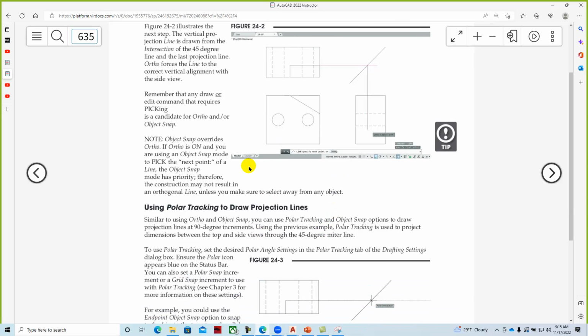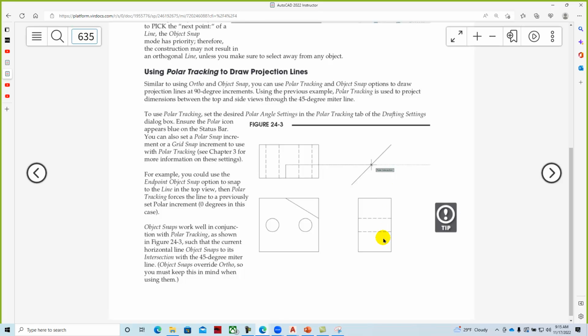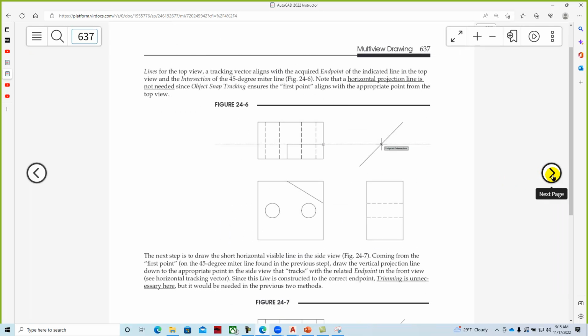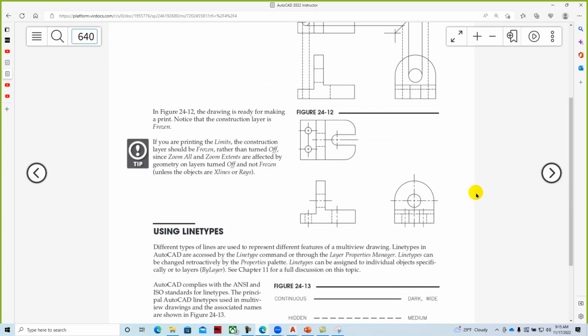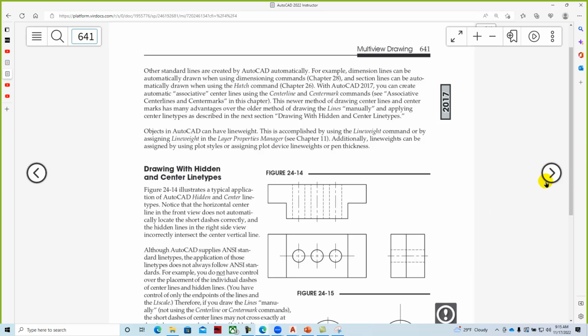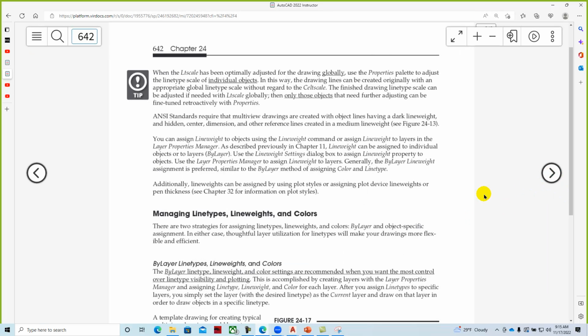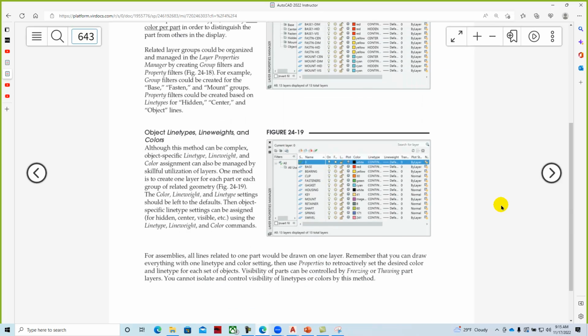And it's called orthographic drawing, and we can use these projection line techniques. These go back to when we used pencils, where you'd have the front view line up with the top view, and then the top view, if you were to bounce off a reference plane line down to the right side view, you have the width and height, and then you have the width and depth, and then you can transfer to the height and depth within the side views. So just basic knowledge of technical drawing as we work with our mechanical and architectural drawings. So that's the reading assignment for the chapter.